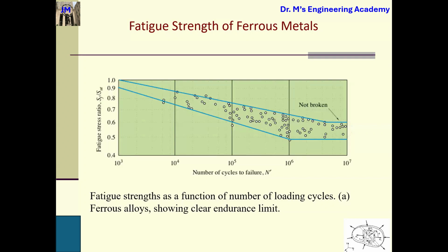Thank you. Once again, endurance limit means that if the stress level you are applying is lower than this value, then theoretically, no matter how many cycles you apply to this specimen, it will not fail.